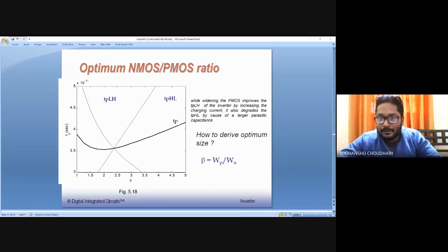That is because of the sub-threshold region of operation of the MOSFET. That is how you are seeing still some current at the output, and that is why the CMOS inverter is still behaving like an inverter. But yes, the current drive, that is the current that is obtained, is very small. The value is very low. So the circuit is very slow because of this, because charging and discharging depend on the current drive. So the circuits become very slow.